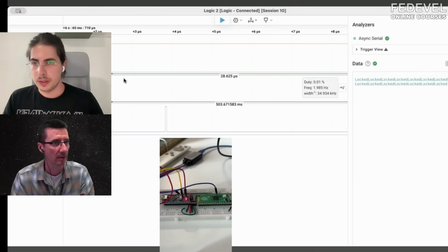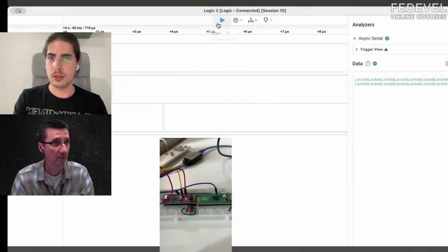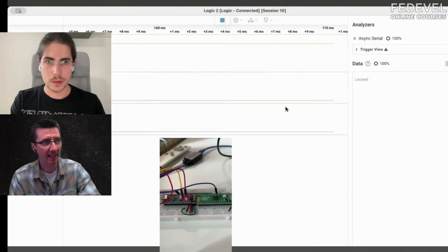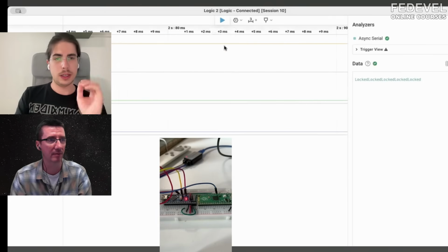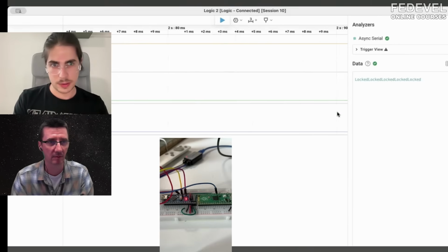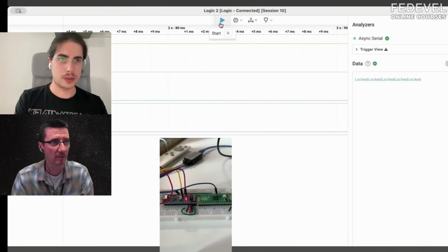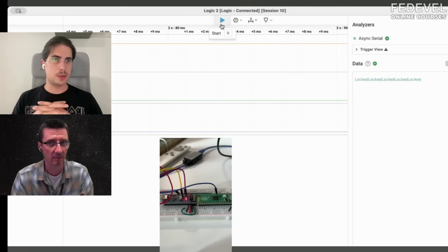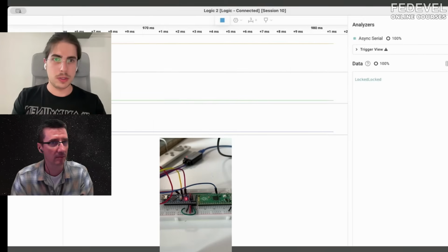Okay. Yeah. But I don't want to get into too much theory right now. Basically, I just want to show how fast it is to attack this device on a simple setup like that. So right now nothing happened, yeah? Right now nothing happened. Right now I'm not doing anything. I paused it. And I will just restart it and let it run. The target is just stuck in this loop where it's locked, because the value is always 255. It's as if we were reading a fuse, and the fuse has a locked value and we can't do anything about it. And now we try to modify this value.